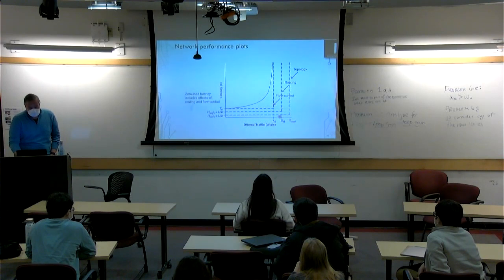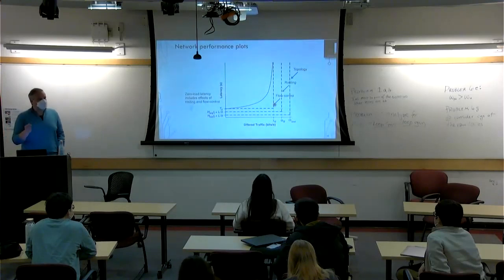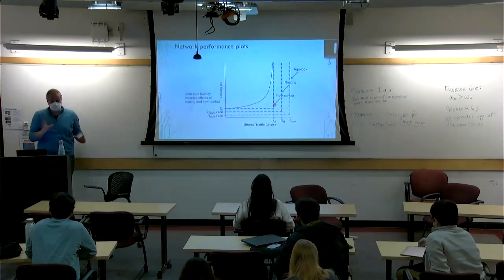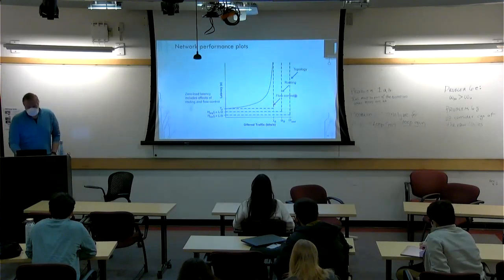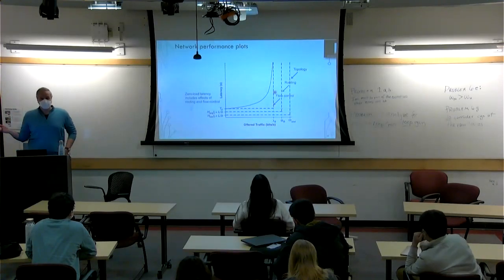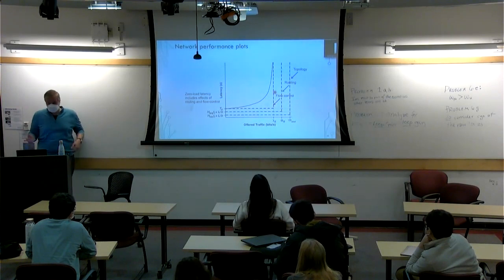The issue is that every time you include this next layer, how the routing is done, how the flow control is done, your throughput also drops. And these are things that are harder to do by hand. You really need to get into the network simulator for a given topology and understand how much this shrinks. You'll see later in some plots that I show you, this can shrink by 2 to 4x, depending on the real simulation and the types of traffic patterns you're running on the system.